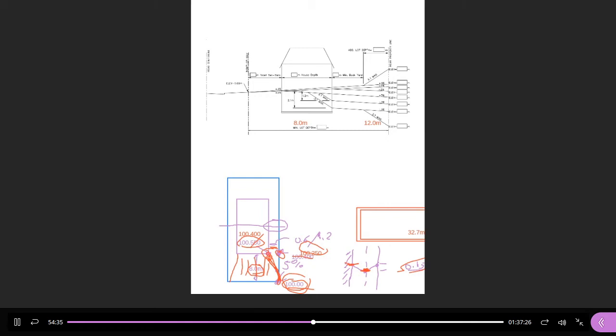All right, so now what we want to do is establish, for the different categories of lot grading, what the elevation difference is going to be between the front of the house, the lot corner, so this point here. I have an elevation at the front, and I'm going to assume it's 0 so that I can do some easy calculations. I want to know the elevation at the back in various grading scenarios. So we're going to do a whole bunch together. You're going to need your calculators. Like I said, I want everybody to crunch the numbers. And this exercise is worth doing at least once so that you can practice.